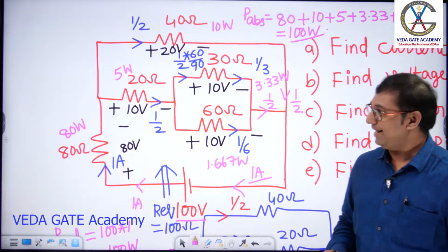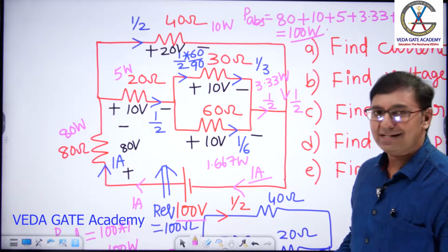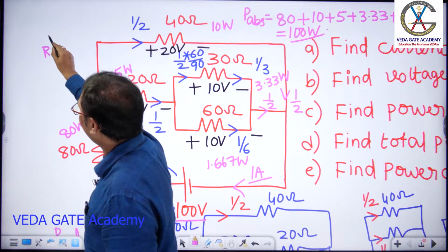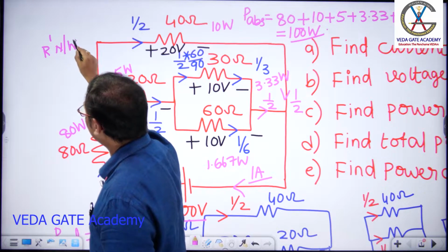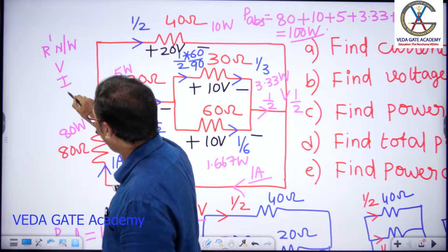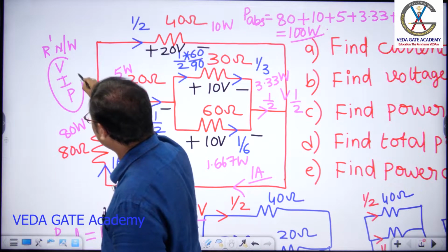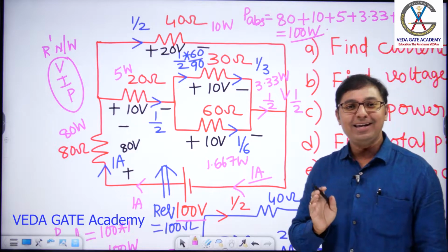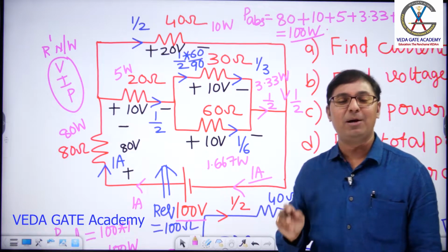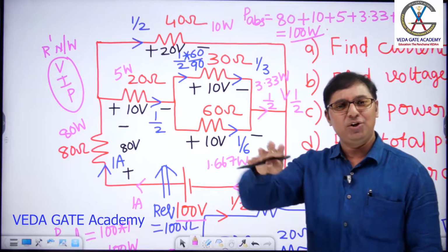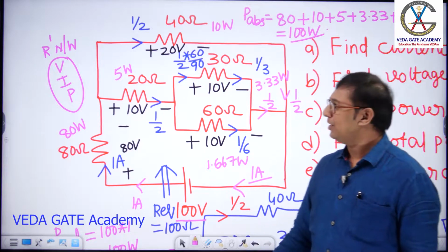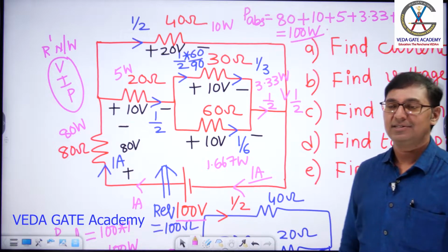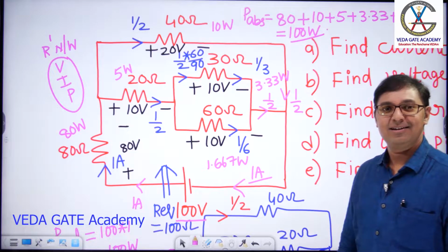Done, sir? Right. For any resistive network, to check whether answers are correct or not, simply follow this statement, very important: verify KVL, KCL and power. You can remember it as a very important problem. Yes, I can say you are perfect with the network subject. If you are perfect with this structure, network subject is easy for you, sir. Done, yes?